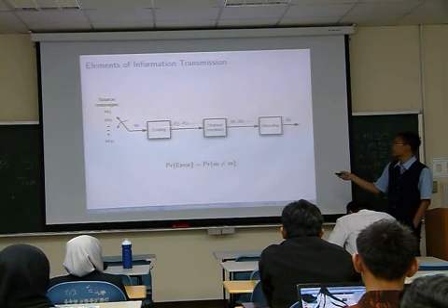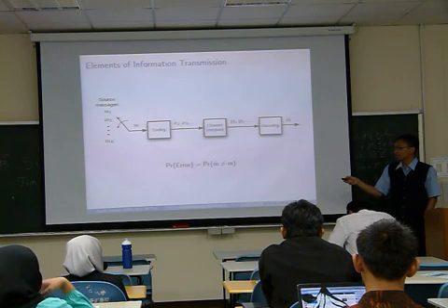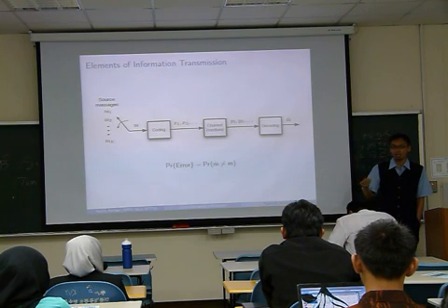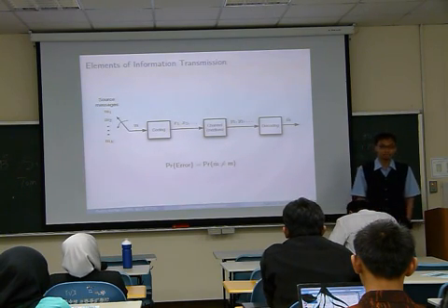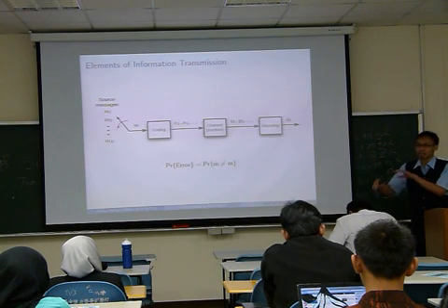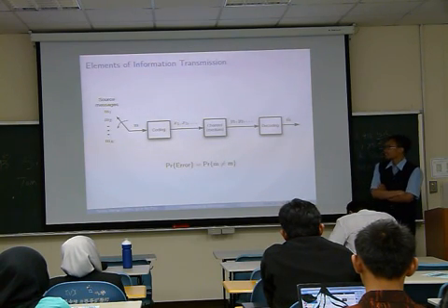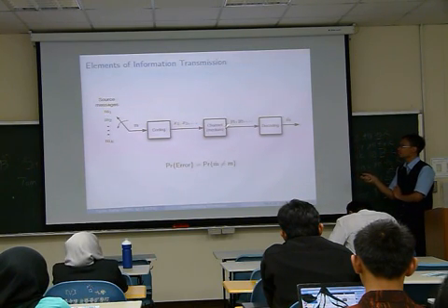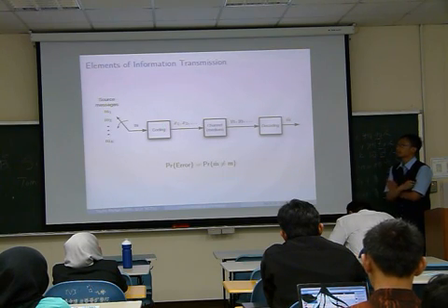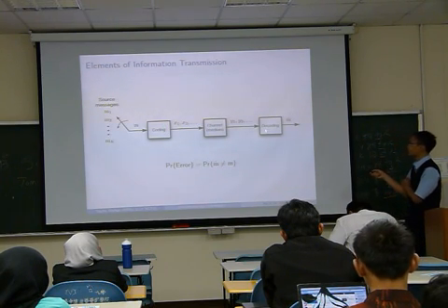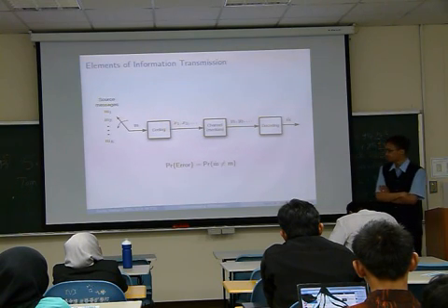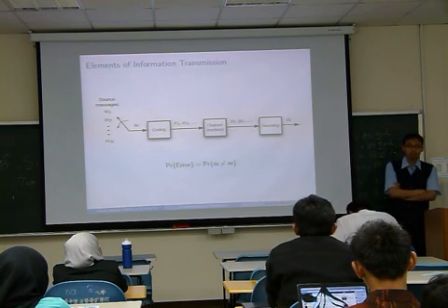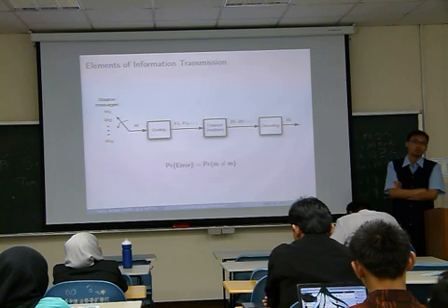Before you transmit, you do coding. Coding is like assigning the bits. You have seen I described something on the bit assignment. That is one example of coding. Okay, so it's not coding in a computer like C++ or anything like that. Then this channel will output something which might not necessarily be equal to the input. And then we have the decoding, which tries to guess what message was transmitted before. Obviously this has an error probability, which is the probability that your decoding output is not equal to the message that you just transmitted. Okay?